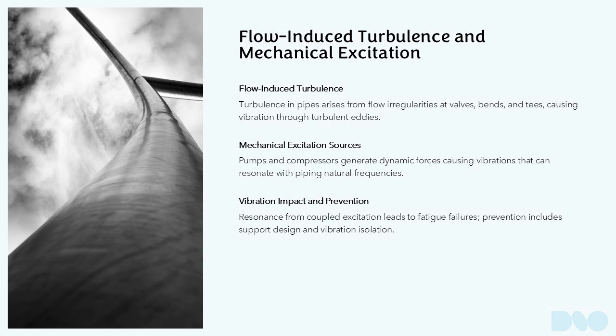Mechanical excitation is another significant contributor, typically associated with reciprocating or positive displacement pumps and compressors. These machines impose dynamic forces on connected piping systems, either directly through suction and discharge lines or indirectly via structural transmission through shared supports. The excitation frequencies often correspond to the machine's operating speed and its harmonics, creating multiple opportunities for resonance with the piping's natural frequencies.